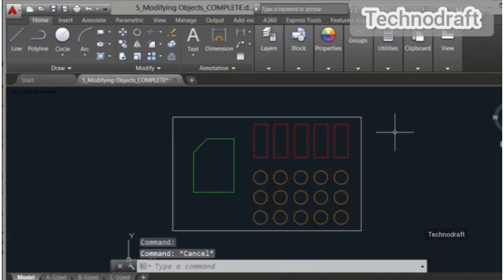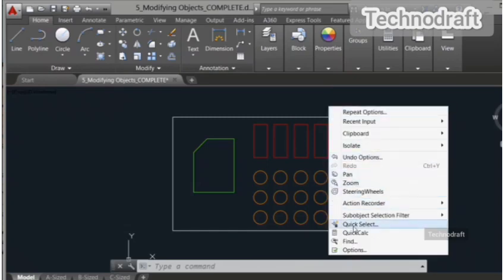You can see that I am removing those from the selection. Now if I want to lose that selection set, again I hit escape a couple of times, and the reason I hit escape twice is once to cancel any commands, and the second is to cancel the selection set itself, just to make sure that you deselect everything in case you move on to a different command.